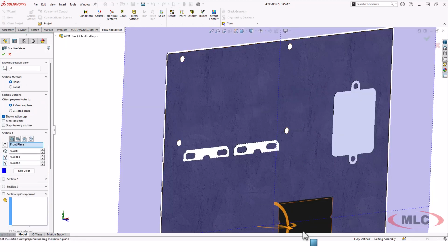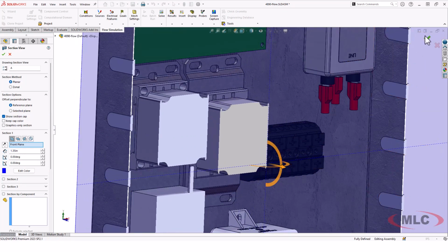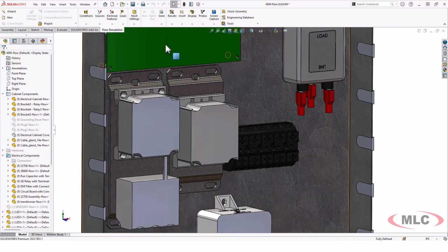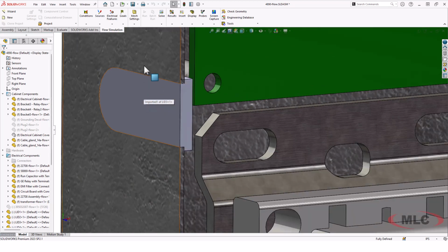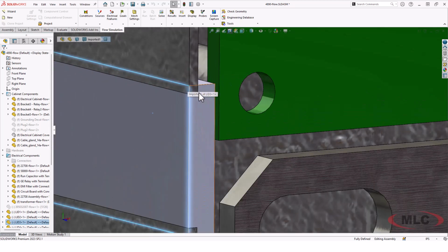But the specific thing I want to show you is, because this is a thin wall, and because I use the lid tool, we have some consequences that we have to at least understand, if not sort of deal with. This first one, I picked the outside face, and what it did is it did an offset entities to the outside, made it a little bigger, and then extruded it down through, so it created an interference. That's okay. I'm not doing any conduction on this lid, so that's not going to create any problems there. But it did poke through the other side.